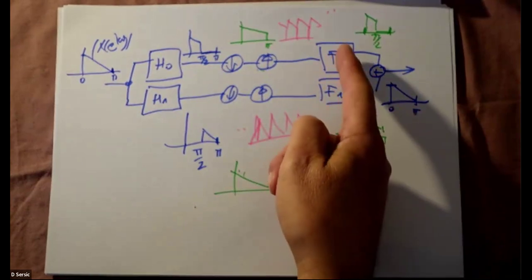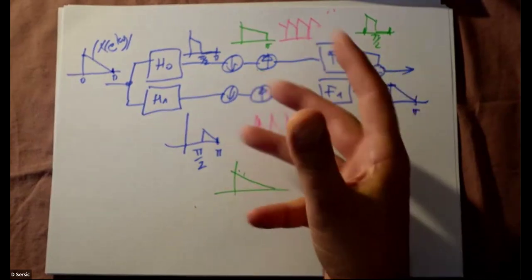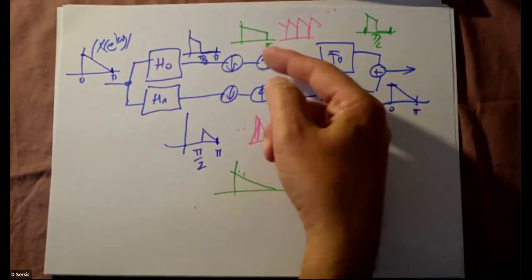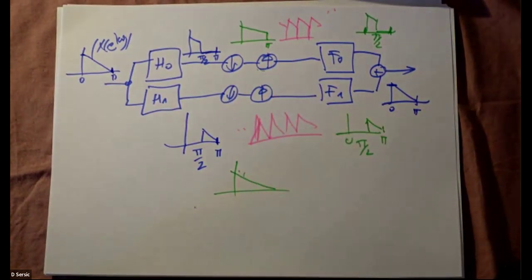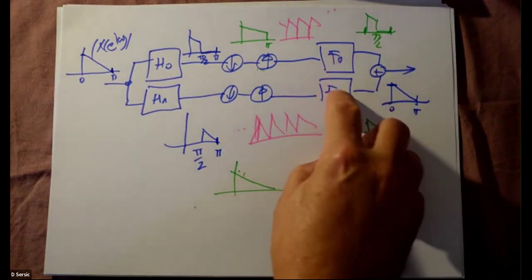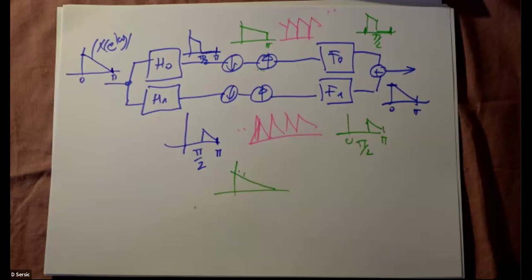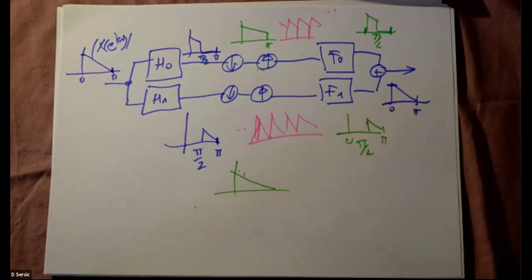The low pass filter and the high pass filter in the synthesis part must kill the repeating image of the spectrum, which was introduced by inserting zeros in between the samples. Now we understand why we need them: to kill the unwanted part of the spectrum and get back to our signal. So I will go back to the presentation.